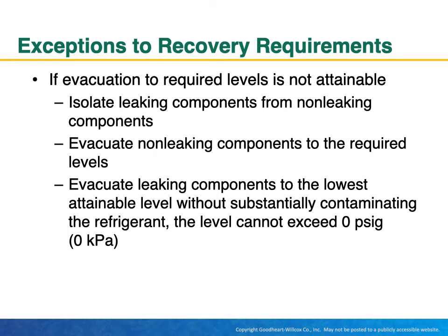Exceptions to recovery requirements. If evacuation to required levels is not attainable, isolate leaking components from non-leaking components. Evacuate non-leaking components to the required levels. Evacuate leaking components to the lowest attainable level without contaminating the refrigerant. The level cannot exceed 0 psig.